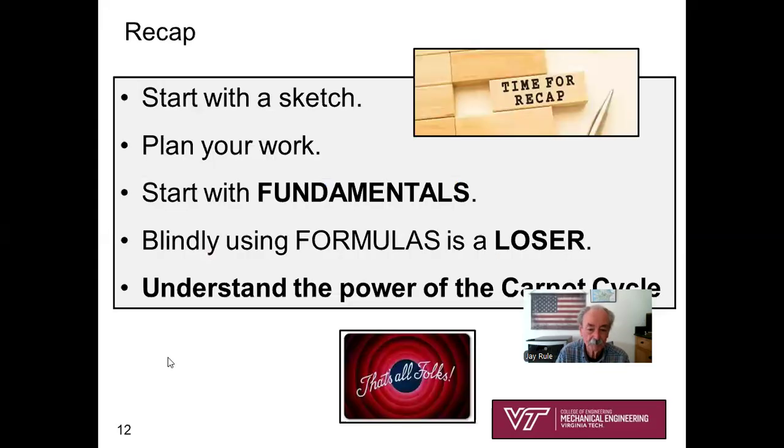Looked tough. What did we learn from working through this? Well, one was we were given a sketch, but we had to study that sketch. We didn't even have to make any other sketches. It helped me to draw that schematic of the refrigeration cycle. That helped me to pin together, I need TL and I need TH for the Carnot cycle. All I need is TH and TL. That's what prompted me, out of the corner of my eye, to see that TL was given as 0 degrees C.